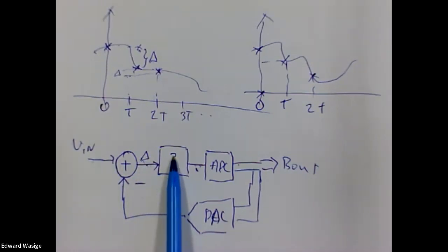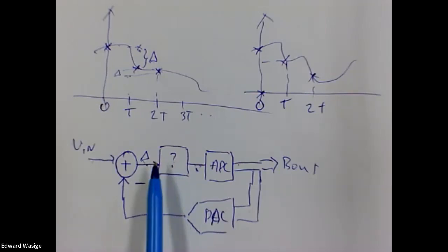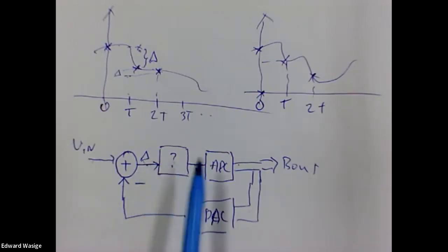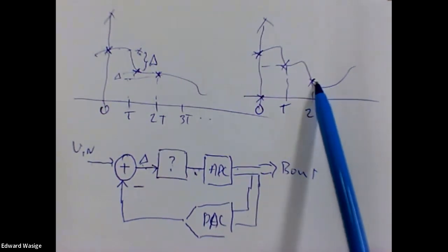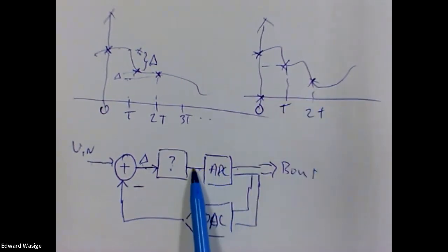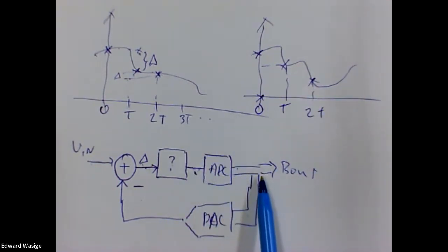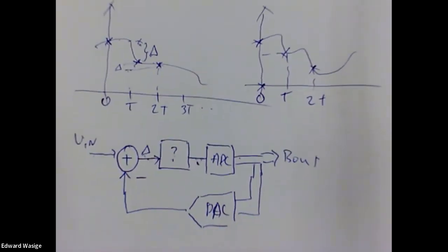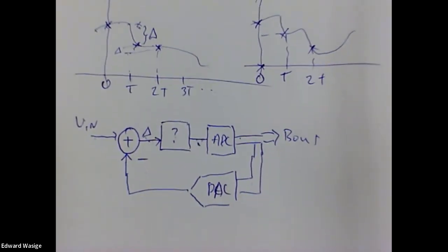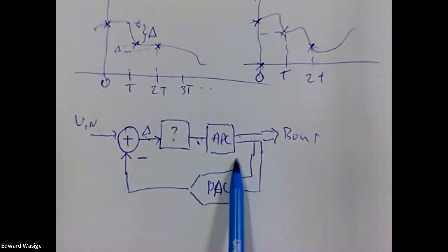We still have the previous voltage in this unit here. So we use that difference voltage to create the new amplitude that corresponds to this new sample. And so we have the correct amplitude at this point. We digitize it, we go out, and then we get feedback. So any question about how this is happening?